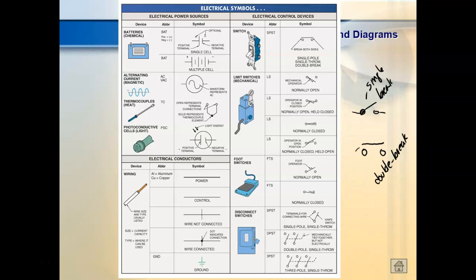What a double break does, I'll show you a double break contact on a relay. I think I passed it around. The way it is, it's springed, so it has the ability to tilt. Can somebody come up and get this? If one side gets stuck, then it'll tilt, and when it tilts like that, it has a tendency to unbreak the contacts. So double break contacts are more likely not to weld together than single break contacts. You can push on one side and you'll see the other side tilts up, and that's the advantage of double breaks. Limit switches, did I show y'all a limit switch? Yes, no?